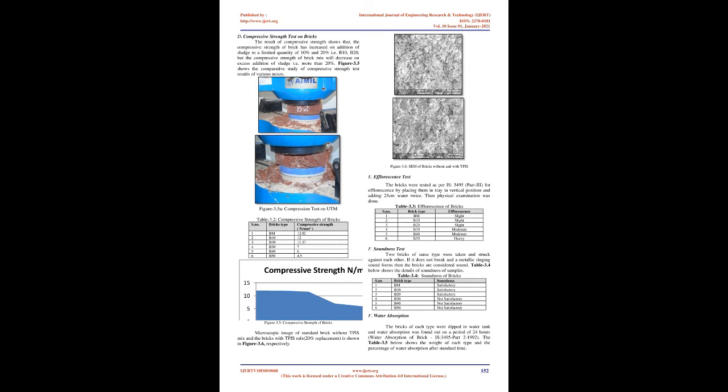G. Water absorption. The bricks of each type were dipped in a water tank and water absorption was found over a period of 24 hours. Water absorption of brick is as per IS 3495, Part 2, February 1992. Table 3.5 below shows the weight of each type and the percentage of water absorption after the standard time.